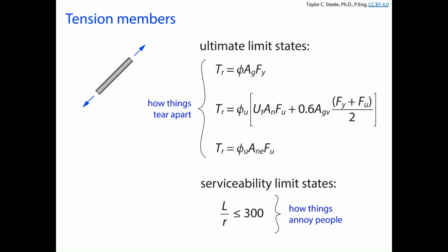Generally, with welds, we are going to see that we don't have to drill holes, and so we get to maintain more of the net section, but there are still shear lag effects that we're going to have to talk about when we talk about welded tension members.